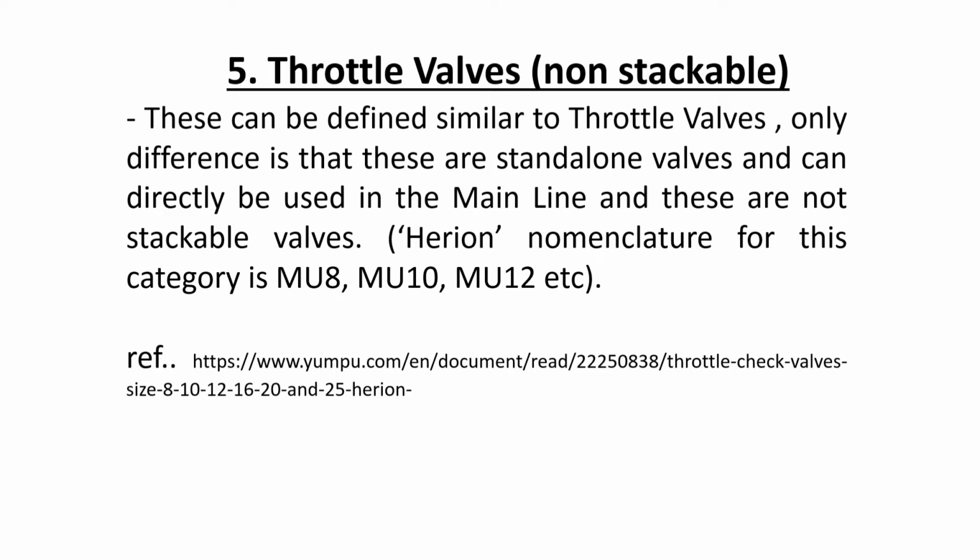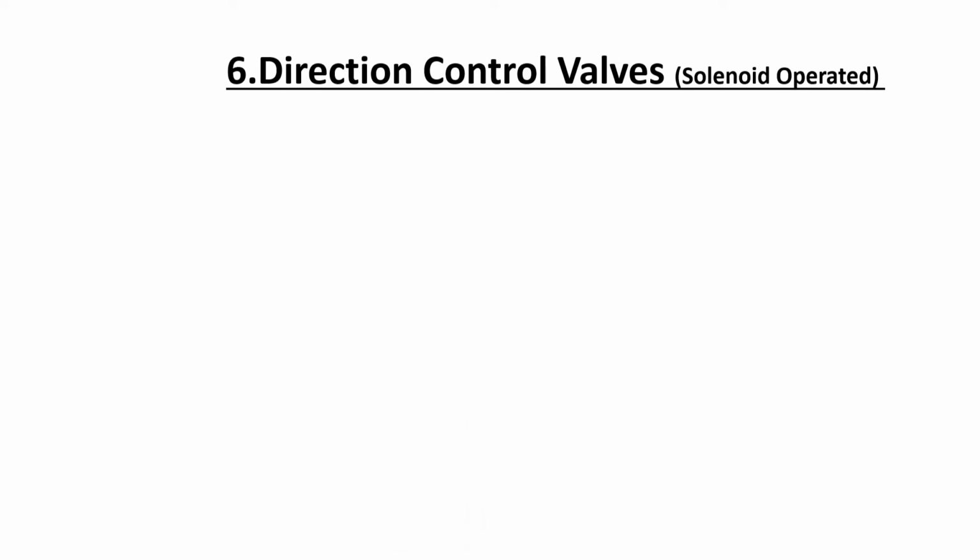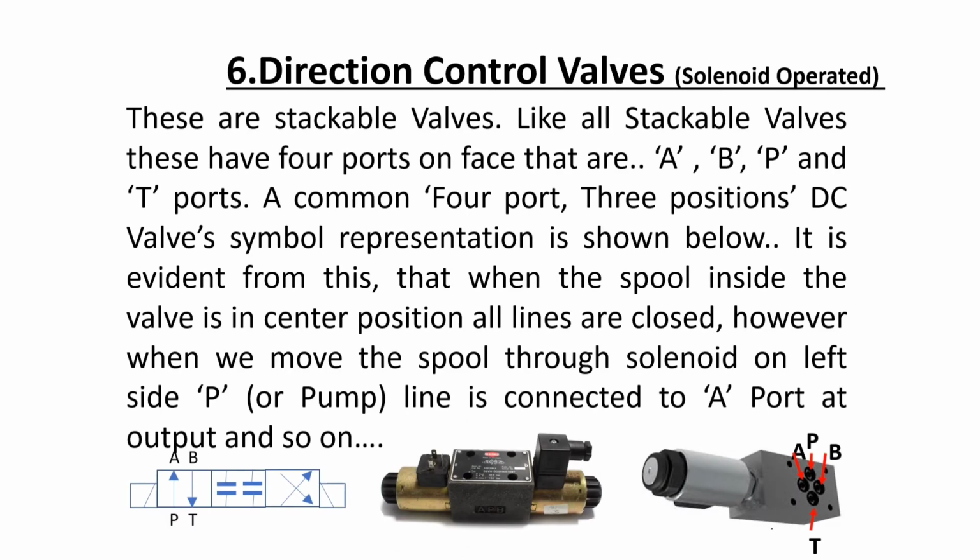Now, throttle valves, non-stackable. These can be defined similar to the throttle valves that we have done earlier, the stackable ones. The only difference is that these are standalone valves and can directly be used in a main line, and these are not stackable. So as you can see, this is in the first slide also, we had shown.